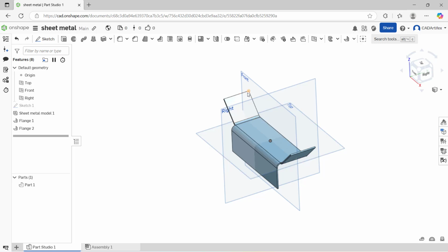Okay, so in sheet metal design, sharp edges can cause issues during manufacturing and may even lead to cracks or unsafe handling. To overcome this, we use the corner break tool, which helps to smooth out the sharp edges by applying either fillets or chamfers.